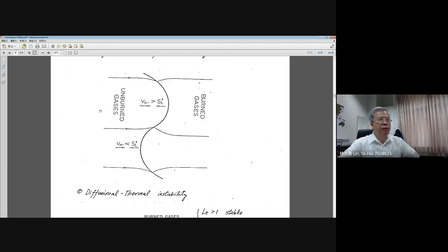And for a given total flow rate, the cross section of the stream tube becomes smaller. Then, thinking about the mass balance, you realize that as the cross section is reduced, your flow velocity will increase. As you move from the upstream side closer to the flame side, you will find that the approaching flow velocity increases continuously.